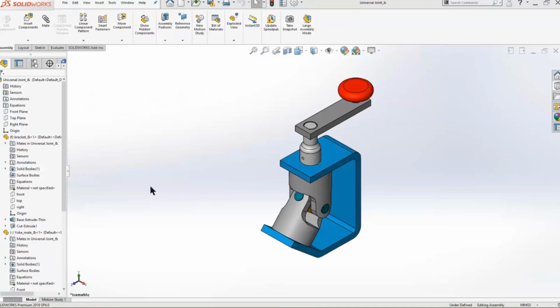Typically when we visualize the assembly feature manager tree, it's more part-centric, where we have the part and then we have access to all the planes and origin features that the part needs. I don't know about everyone else on the webcast today, but when I build an assembly, I spend most of my time adding components, working with the mates, and a little bit of the time editing the features of the parts themselves. So there's actually a way to flip the feature manager tree in the assemblies and put the mates at the forefront and put the features behind the scenes a little bit.